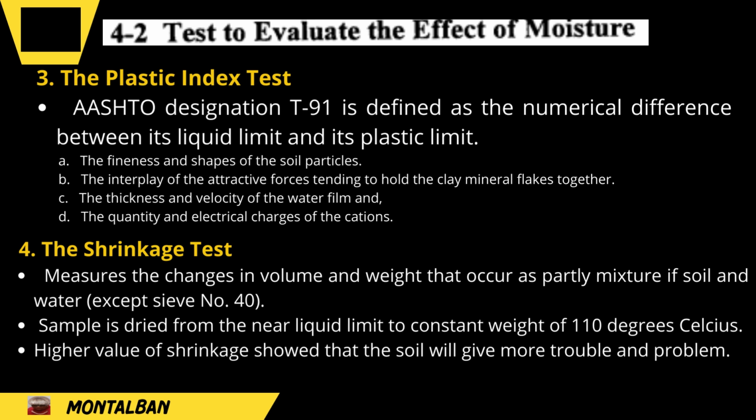Experienced road builders use the plasticity index as one control in selecting the materials for underpavement. A common base course material specified requires the plasticity index not to exceed 6, while others insist on not greater than 3. Soils with high plasticity indices are much less acceptable for subgrade and base course.